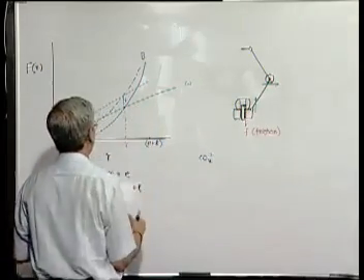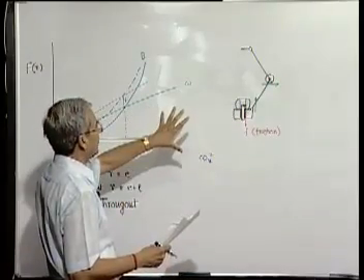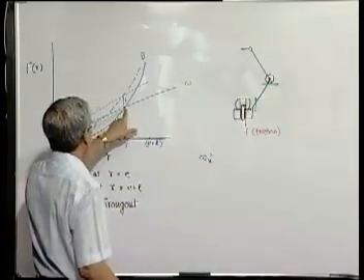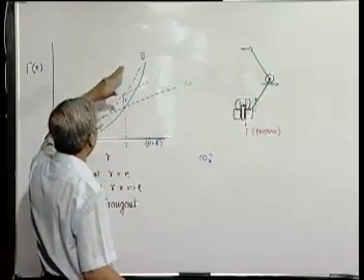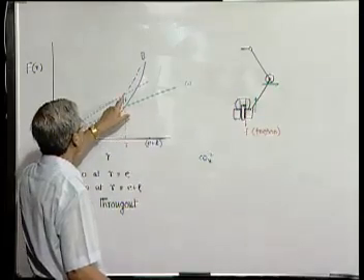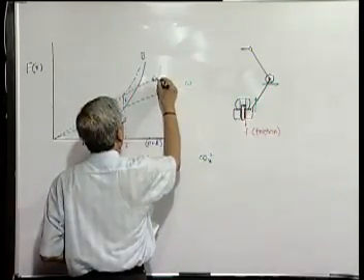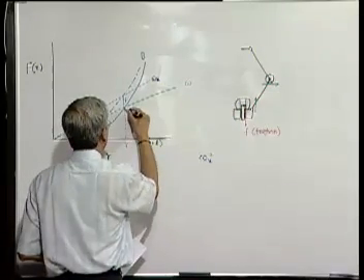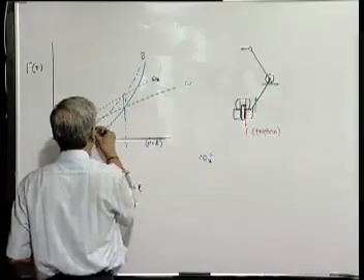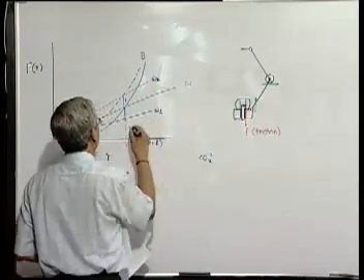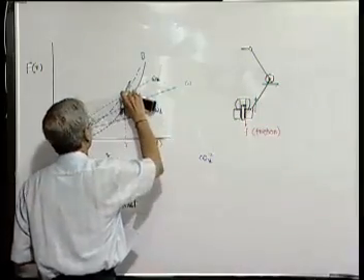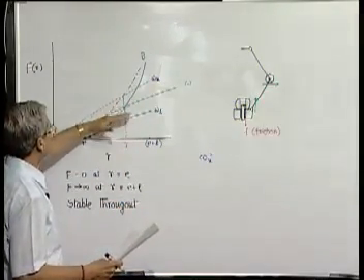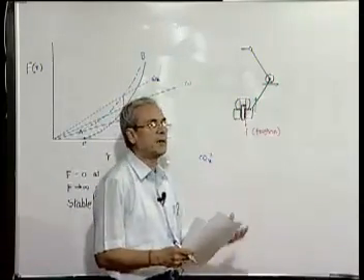at this particular rotation, therefore radius, that means the governor will be at one location, though the speed may vary, because the friction will take care of that variation. So at this radius, when the governor is rotating, the maximum speed at which the governor can still be at this location is this point. So this will be your upper limit of the speed at which the governor can remain at this radius r. Similarly, what is the lowest possible speed when the governor. So therefore there is always a certain amount of insensitivity, that means the speed of the governor can change from omega L to omega u, but still the governor will remain at the same location. That means it becomes slightly insensitive.